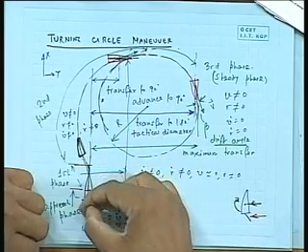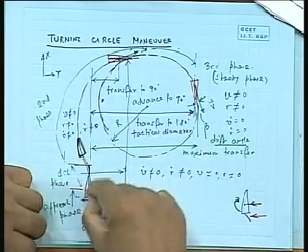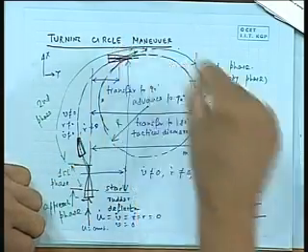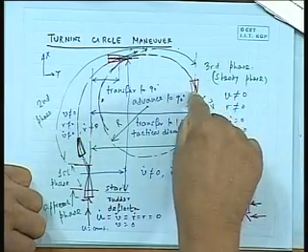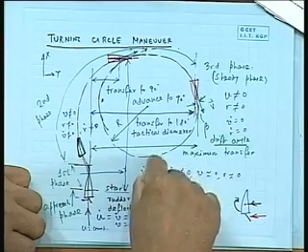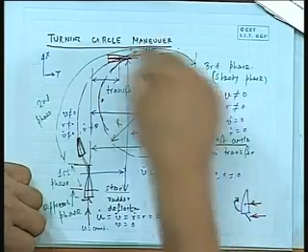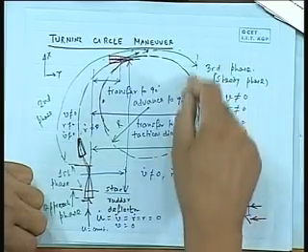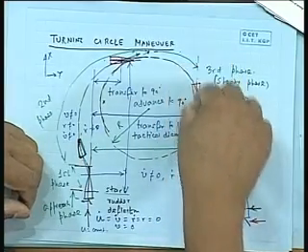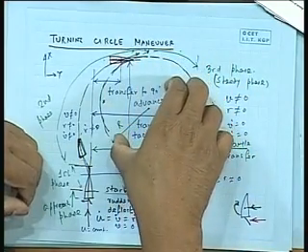And you of course also have a record of time, at what t this occurred: the time for heading of 90 degree change, time for heading of 180 degree change, and if you want time for 270 and all, but normally people don't go beyond that, because this completes a U-turn. After that you don't want to keep turning in a real atmosphere. There is no practical interest beyond that point. So you do that only to find out the steady turning radius, but then you end the test. No, you don't turn, there is no point.